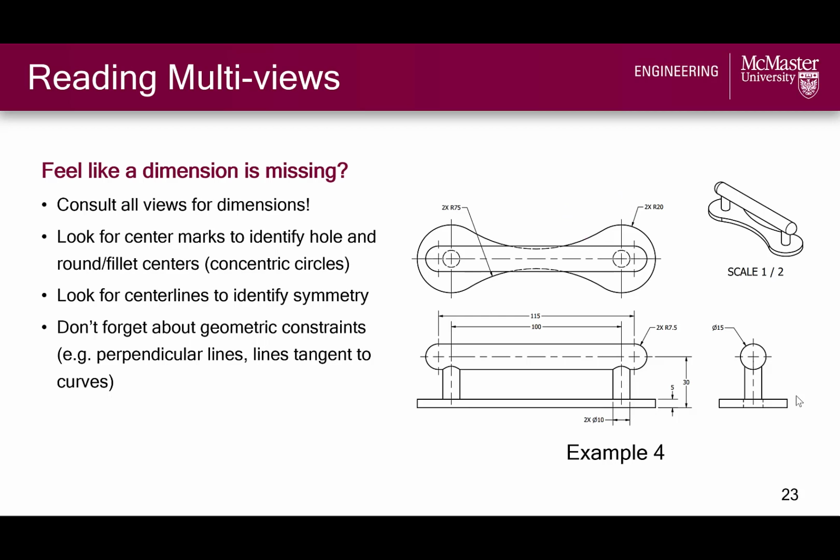When it comes to the center marks on this top view, we can see that the round base end circles are concentric with the handle mounts since they share the same center mark, and this other center mark corresponds to the rounded ends of the handle, which we can also verify from the front view as well. So these are some tips to keep in mind when you're reading drawings for part modeling.